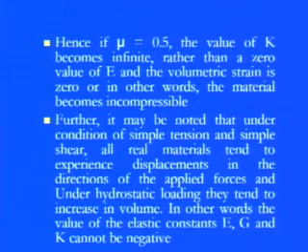Further, it may depend on whether the condition is simple tension or simple shear. All the real materials tend to experience displacement in the direction of the applied forces, and under hydrostatic loading, where equal components are there in all three mutual directions, they tend to increase in volume. In other words, the elastic constants, either E, G or K, cannot be negative. The meaning is pretty simple: any material under a state of hydrostatic loading always tends to be positive, irrespective of whether it is the Young's modulus of elasticity, the shear modulus of rigidity, or the bulk modulus of elasticity.